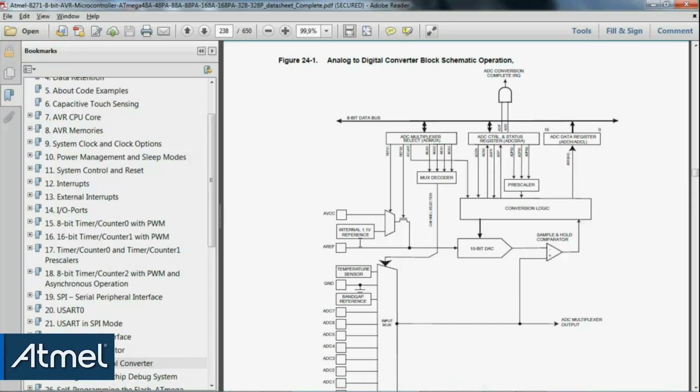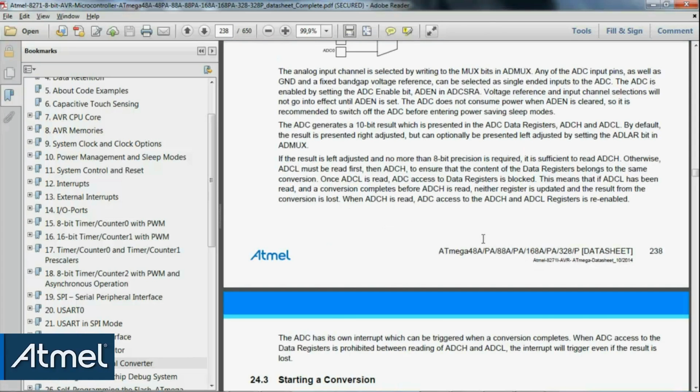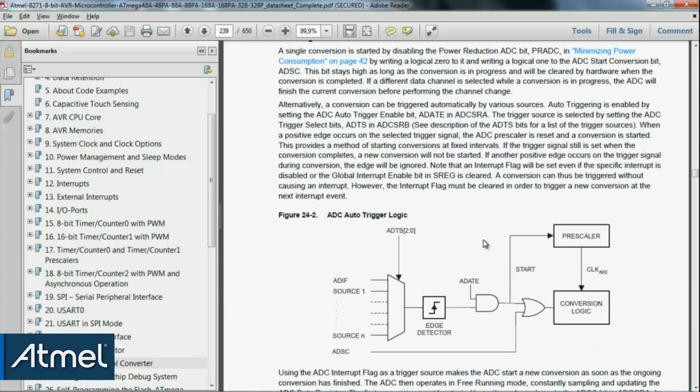available to us. There's a control and status register, which is involved with a prescaler of the clock to the ADC. And then finally there's a result register. You can see that it's 16-bit because 0 to 15, but remember it is a 10-bit ADC. So let's scroll and look for some interesting things to point out.